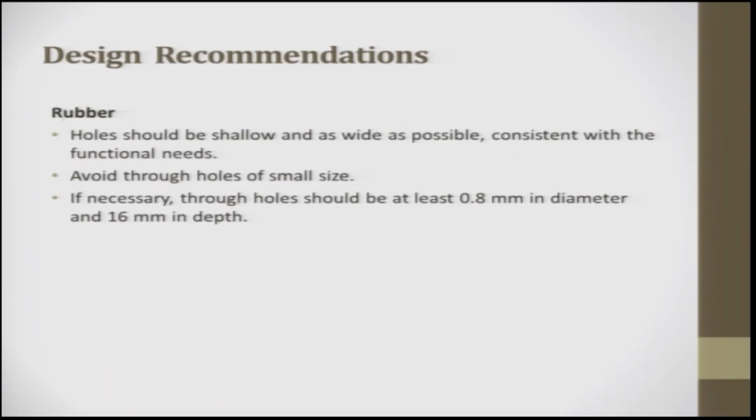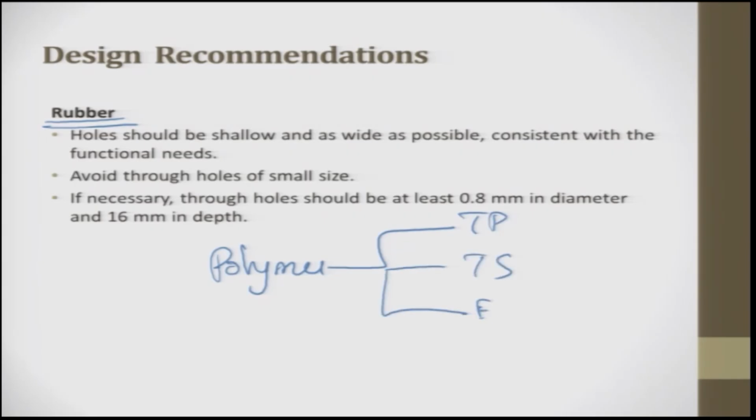So, rubber is one interesting material, but if you look at the periodic table, there are so many elements there, right, and to a large extent you have metals, rare metals and rare earth metals and this and that. In the entire periodic table you will never have a slot for polymer, but today polymer dictates the world. 30 to 40% or even 80% of the domestic products are made out of polymers. Okay. So, in polymers we classify them into 3. One is thermoplast, one is thermoset, and the third one is elastomer.